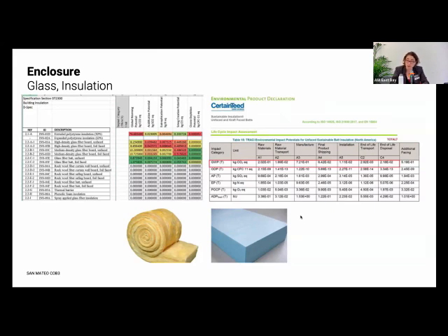And so teams in each of their projects did analysis to look at both what material was available in EPDs, what were the global warming potentials, what were the service lives for all those materials, and then we ran an analysis to say what really are the right products that we should be using. First, are they fit for purpose? And then second, if they are fit for purpose, what is the best of class in that group? Everyone that was on our list for preferred manufacturers for a spec that has been tried and true for years, if you didn't have the required documentation that we could do this analysis, we wrote you a love note and said, we would like this information. Transparency is important. Will you give us this information?